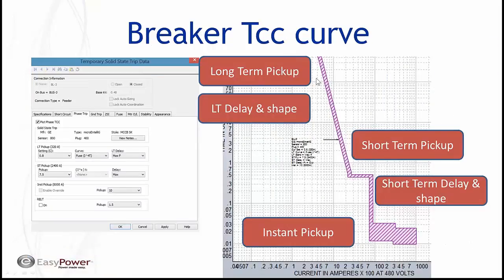Likewise on breakers, this is the TC trip curve, where anything to the left, any current for this amount of time, so if let's say this is 1,000 amps for 0.1 seconds, if we saw that event, it would be to the left of the trip current for this breaker and consequently would not cause the breaker to trip. On the other hand, I take that back, so this is 1,000 amps, 100 times 100 would be 10,000 amps. If we saw 10,000 amps for 1 second, it would definitely cause this breaker to trip.